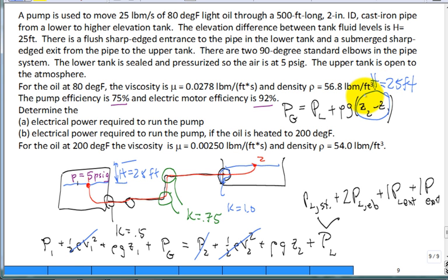And then there's one other term, and you bring this P1 over, it's minus P1. Why is there a minus? Keep track of the minuses and pluses, but having a pressurized lower tank helps push it up. So that 5 psi G is helping it go. So that's helpful, true? I think once you get that, then you said, hey, I've done these loss coefficients before. It's pretty straightforward. The only challenging part is making your units.